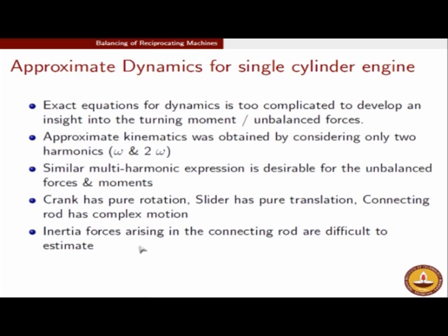So, the inertia forces will require us to find, let us say, the acceleration of the center of mass of the connecting rod. Unfortunately, that formula is not a very compact, not a very simple formula to represent. So, this is where the difficulty lies in the exact dynamics, that the complication lies in the kinematics of the connecting rod, which does not permit us to find how the acceleration of the center of mass is behaving with time. That is what we will try and mitigate in a simplified analysis.